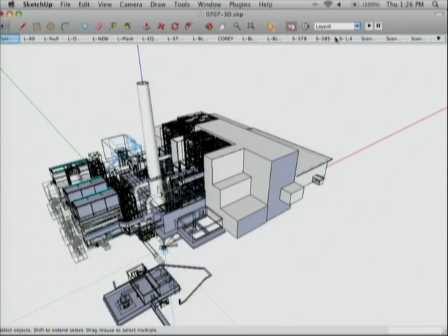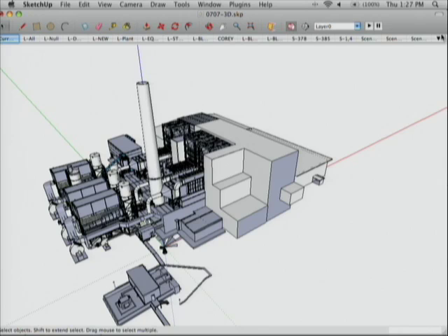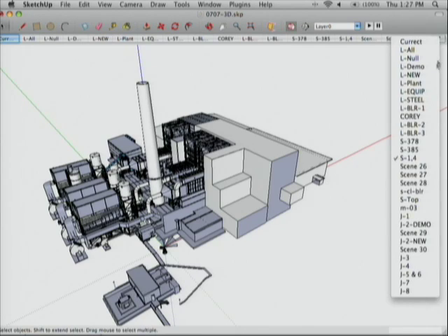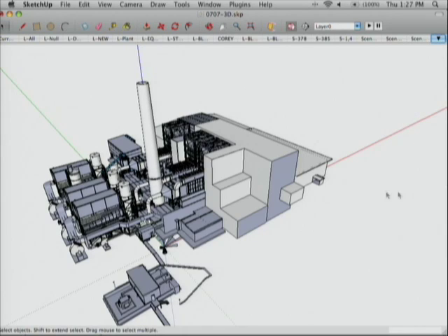Sections are incredibly helpful because I can eliminate a ton of geometry whenever I want to look at stuff. So I set up sections all the time that will allow me to filter out information I don't want to see. And sections are, I guess the right word, kind of a dirty way of making the model smaller, because it's not really organizational. You could have a big model all in one layer and use sections. But you shouldn't forget about them because they're really good.